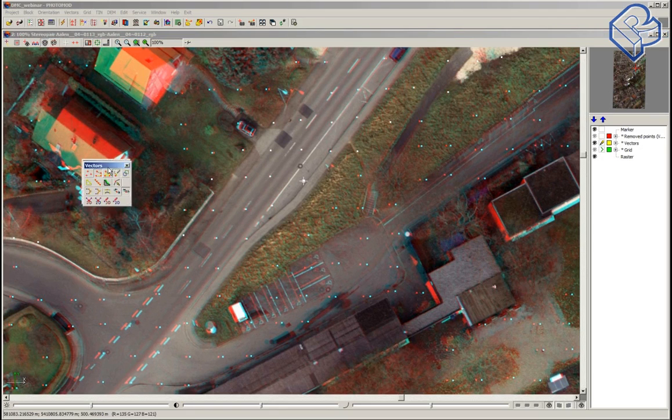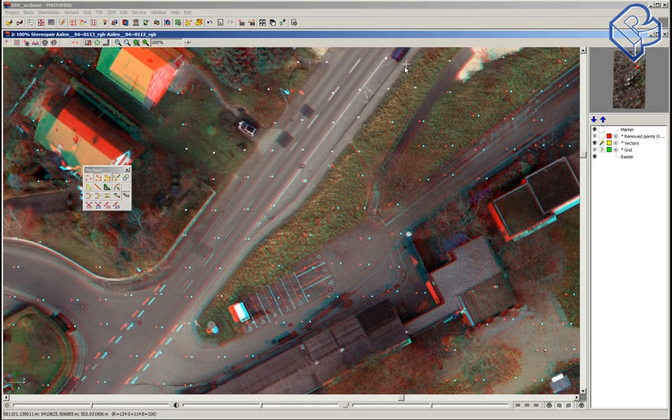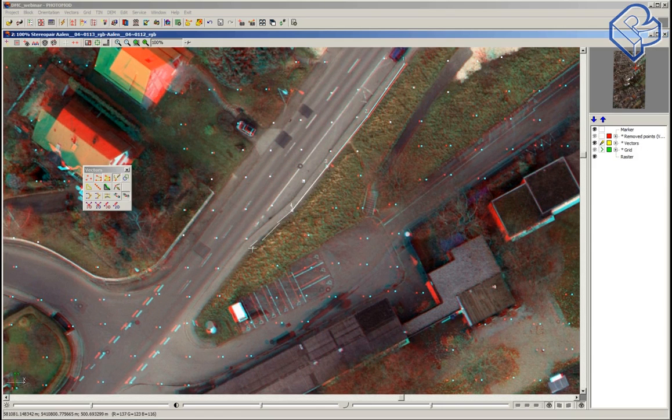In vectors toolbar, choose this mode. There is for points, for polygons, and for line. And let's create the new line. With insert button, we add a new vertex of object and just create this line.